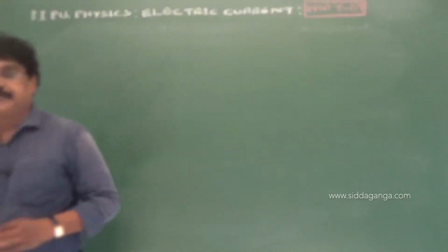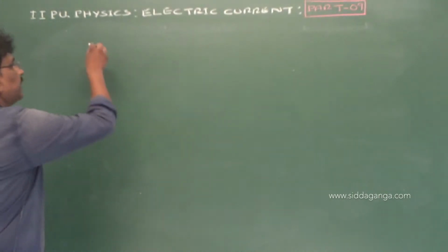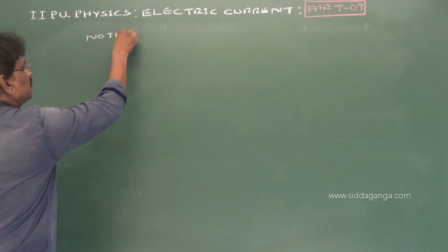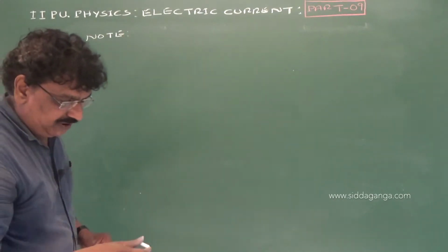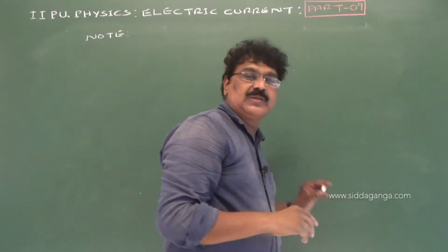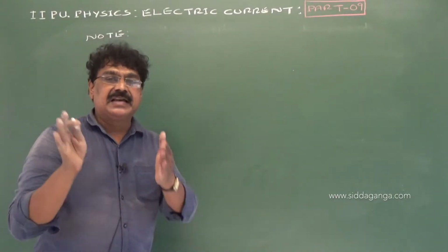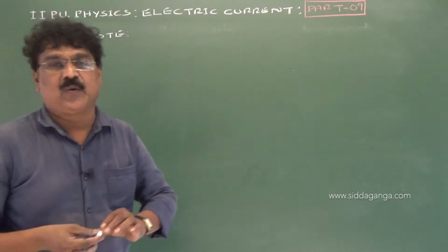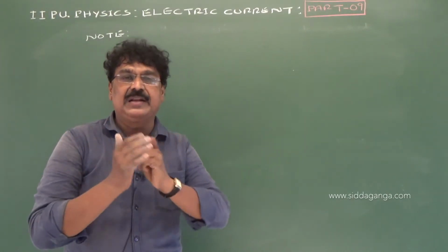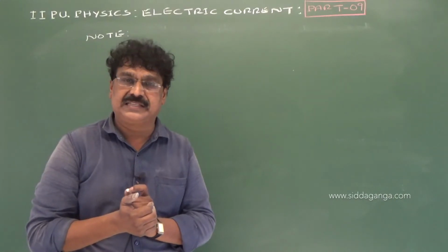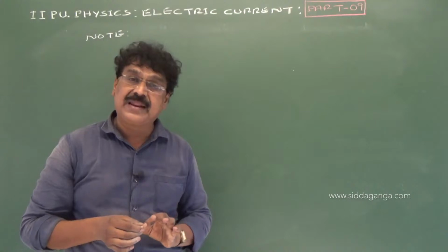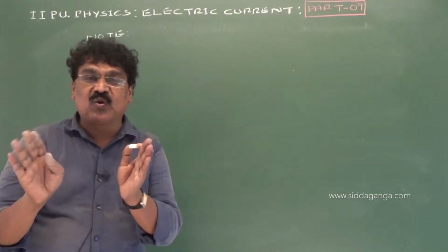Now another thing here, one thing has to be noted. So far, all those resistors we have discussed have resistance greater than 10 ohm. But if the resistance value of a color code resistor is less than 10 ohm, then it has no fourth band.